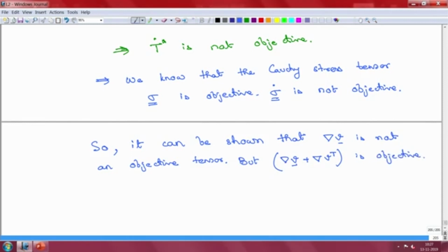So, in the Navier-Stokes equation, this quantity, almost all books would call capital D. The Navier-Stokes equation is given in the form of this capital D, and now you can probably appreciate why, because you cannot just take the gradient of velocity, since that is not an objective field. It also comes from other reasons which converge to the same idea, but this quantity is objective, and to create a good working constitutive relationship, let us say for Eulerian fluids or for an Eulerian system, you would want to use D.